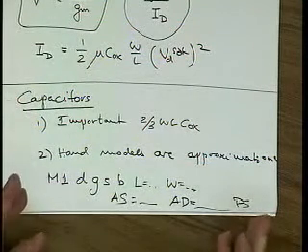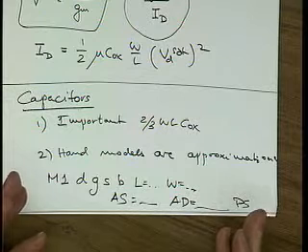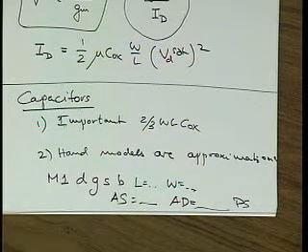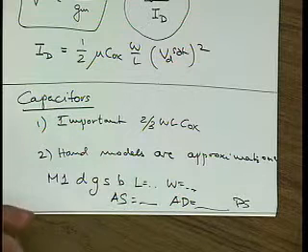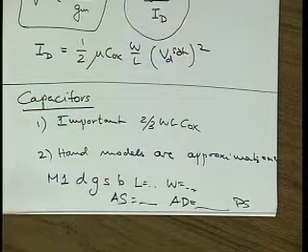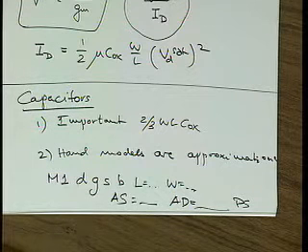So you're familiar with that, right? Okay. Specify those, because the default in SPICE, or in most versions of SPICE anyways, is that they're all 0. And you're really fooling yourselves if you do that. A very common mistake in design.